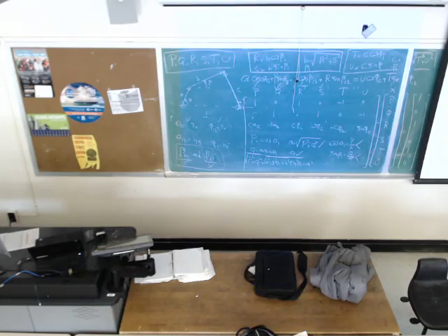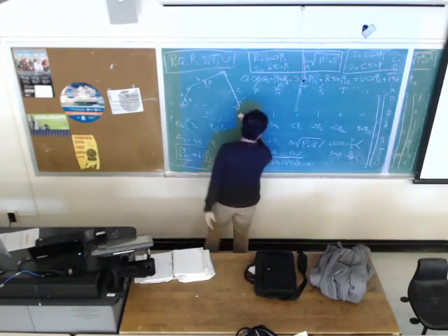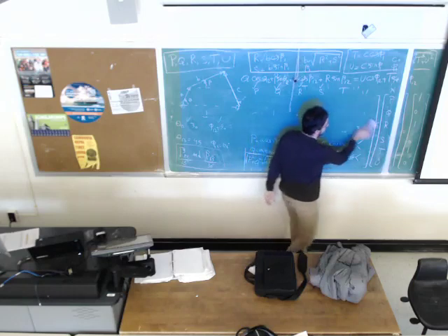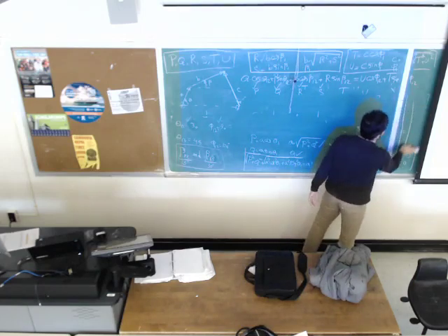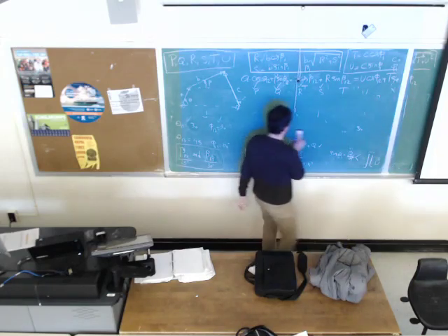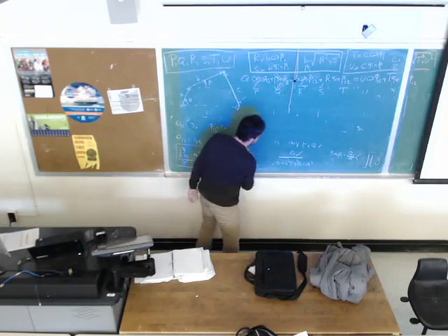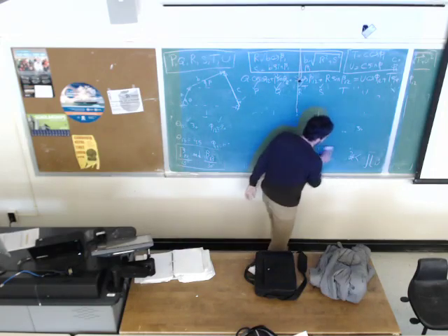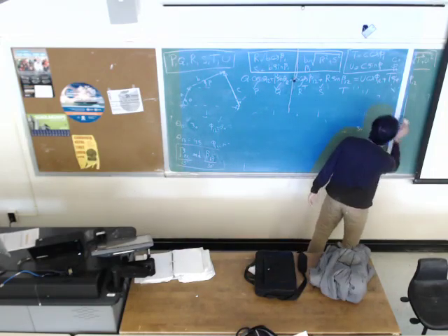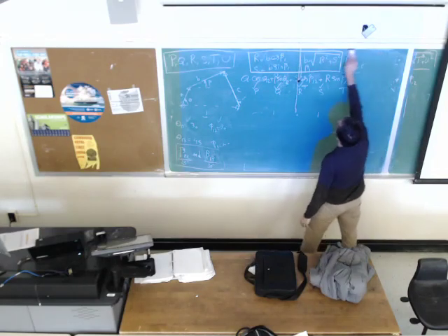And when it goes by 90 degrees, we would like S3 minus S1 to be 3.5. This is a function generation because we are given the correlation between the input link and the output link, and we want to do it by the analytical approach.